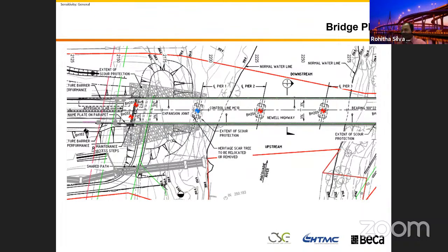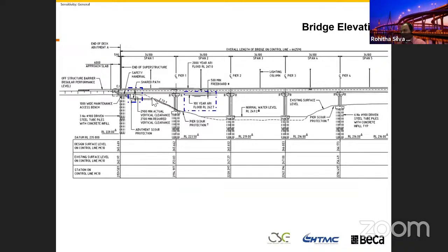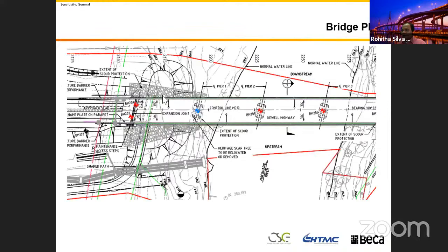When you are building a bridge, in this one you can see there was elevation, and there is a batter down here. Because of that, when you build a bridge at a higher level, how are we going to match both grounds together? Otherwise you can't build a bridge here and leave the ground without stabilizing it, then it will fail. The bridge will not fail, but the road and other things in the surrounding bridge area will fail, and then automatically you can't access the bridge. No point having a bridge if you can't access it. So all these elements we're going to put in here, but we're going to see them in detail. Any question up to now?